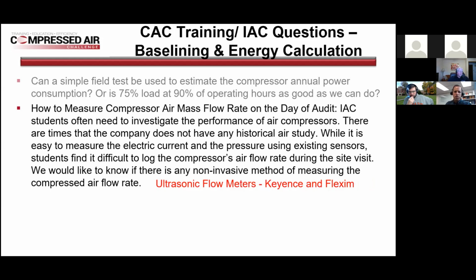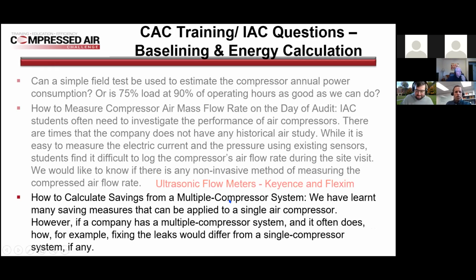And there are some ultrasonic flow meters. These are two of them that Frank Moskowitz, my friend and instructor, I reached out to him because I knew he had done some benchmarking to compare those to an actual hot wire anemometer, and he's found these two to be pretty accurate and reliable. So again, this clamps on the outside of the pipe, and it does not require any intrusiveness. The cost I'm not sure of, so it might be something you just want to rent. That's what he said that he does. But I did want to let you know that these are available, and there is something that we can go through and use.